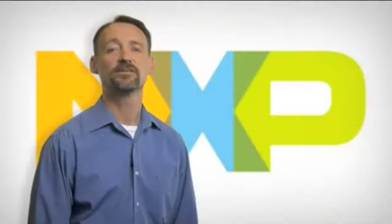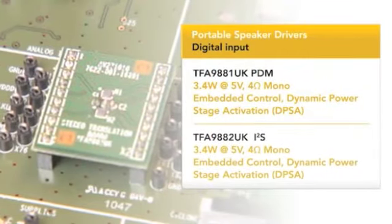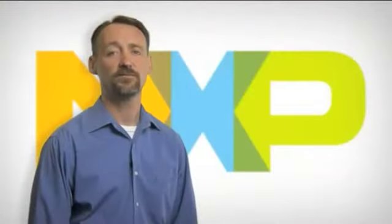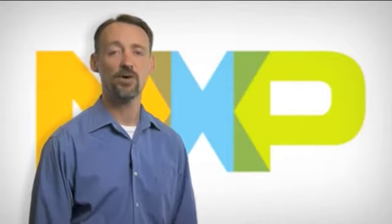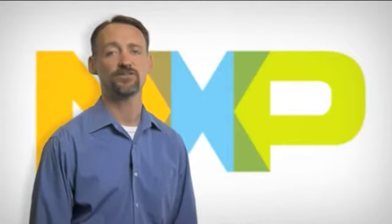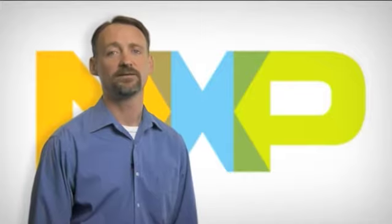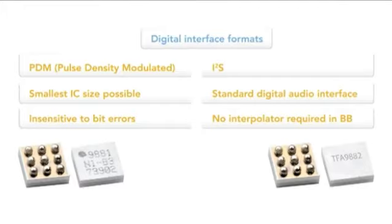In particular, today we will focus on the TFA9881 and TFA9882. These amplifiers both feature embedded control and dynamic power stage activation, making them the smallest and most efficient in the industry. The difference between the two is the input format. The TFA9881 features PDM, or pulse density modulated input, and the TFA9882 features the more standard I2S format.